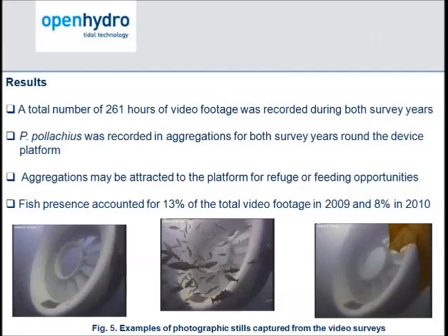What we have observed is that, as you can see from the face of the turbine, it's a very solid structure. And what we see hydrodynamically from the computational fluid dynamics that we do is that the velocities on the lee side of the turbine tend to be much slower. We get a speeding up of water through that center open hole, around the outside and over the top of the turbine. But at the back of the blades, in the lee of the blades, there is a reduced velocity. And we pretty much suspect that will be in both cases, whether on the ebb or the flood, we're going to see a slowing of water and some opportunistic feeding ongoing. But again, it's another area we need to look into.